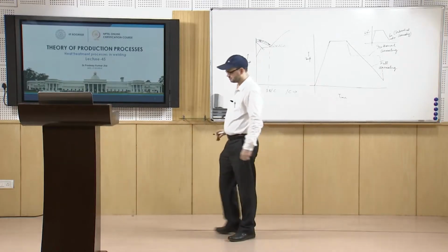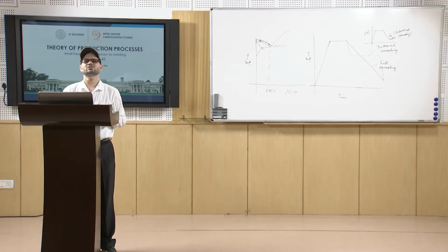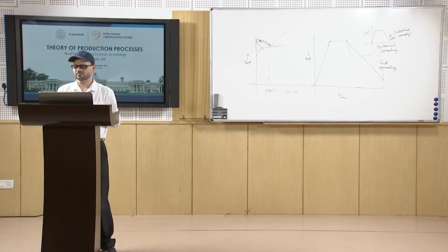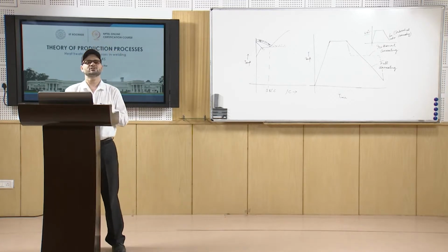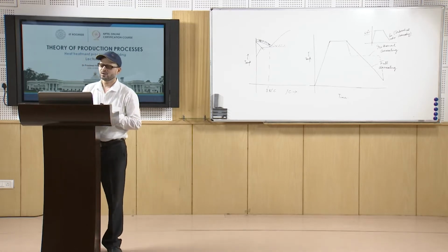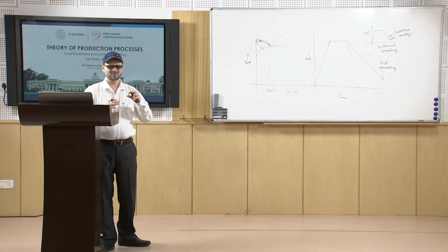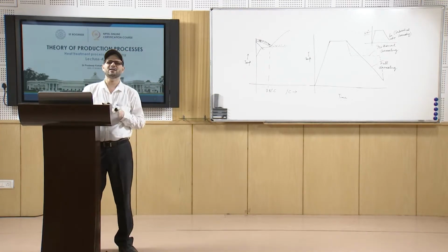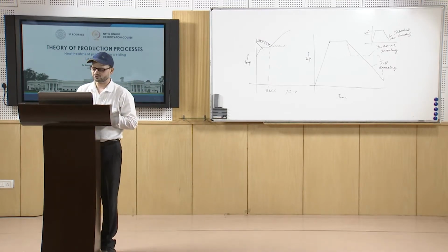Now, after annealing, you have other heat treatment processes, which are normally important in the case of welded specimens, and one of the important ones is spheroidization. We have already discussed the spheroidization treatment. In this case, as we discussed, the cementite particles transform to a spherical type of structure.